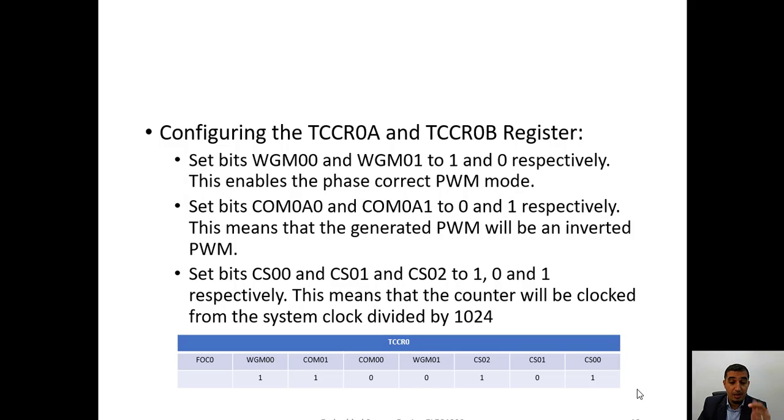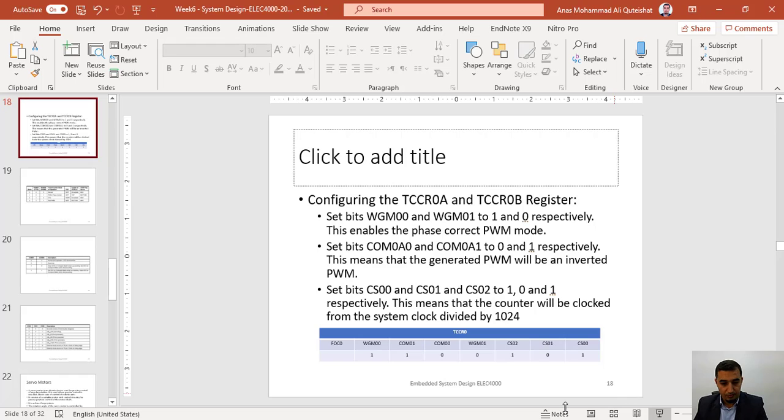What we did in the lab is put the timer counter control register 0 to a value, and we just changed the value of the OCR register. These are the two things. The lab was 3 lines of code. The timer counter control register 0, the timer control register 0, and the mask register, we put them all to zeros. Three lines of code. Okay, doctor, I understood.